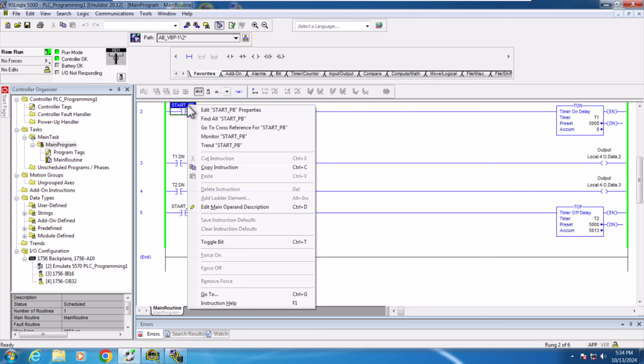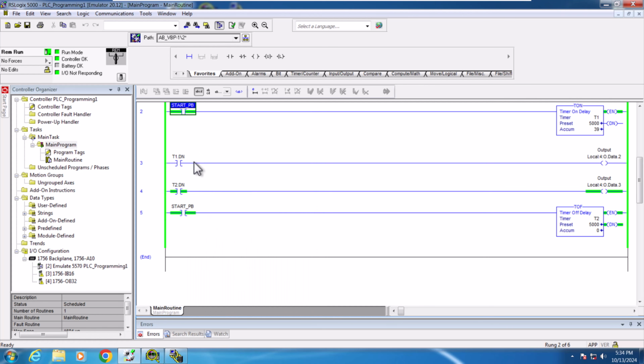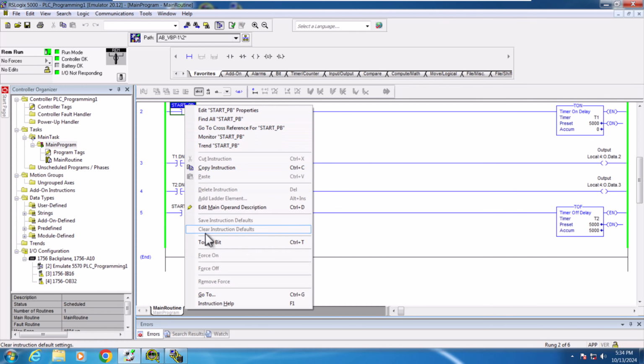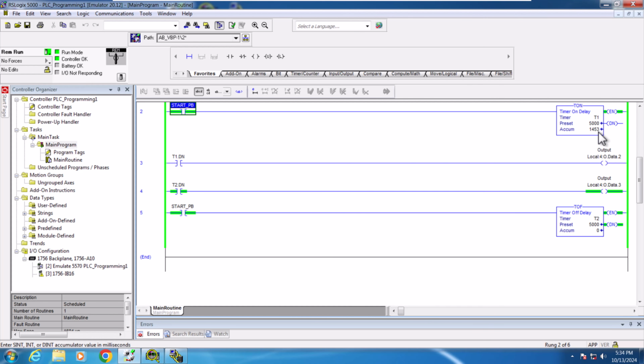This clearly indicates that the on-delay timer energizes the coil after 5 seconds, while the off-delay timer de-energizes the coil after 5 seconds. This behavior highlights the fundamental differences between the two timers and their respective roles in the control logic.